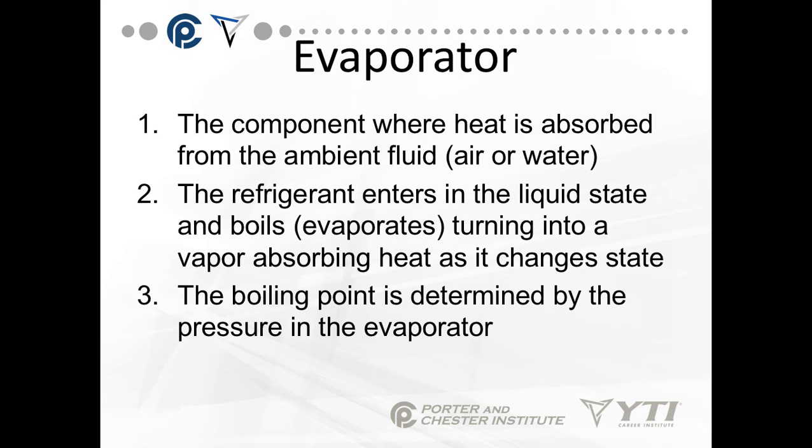The evaporator is my final major component that has to be there. It's the component where heat is absorbed from the ambient fluid, which could also be air. The refrigerant enters in a liquid state, boils off or evaporates, turning into a vapor, absorbing heat as it changes state.